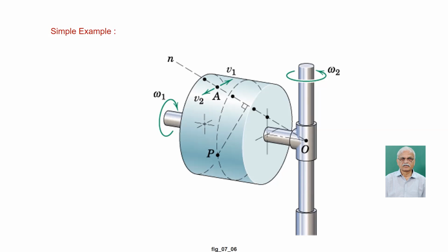If you trace these points on the body, we used to call it the body centroid. Here we call it a cone, the body cone. It happens here as a cone, but it can be a surface also. So all those points, if you trace them on the body, we call it a body cone. And if you trace them in the fixed space, big XYZ, then we used to call it a space centroid. Now we call it a space cone.